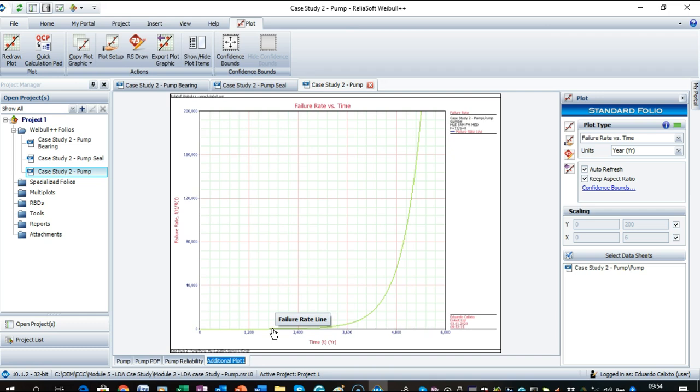I will look at all equipment, but especially the bearing and seal. And if I do not detect any failure in the seal, and I do not have the data for this specific definition of components in my database, I just do some inspection at 1.2, 1 year, and then I will wait for, let's say, 1 more year to do another inspection, and then probably that's a very dangerous game.